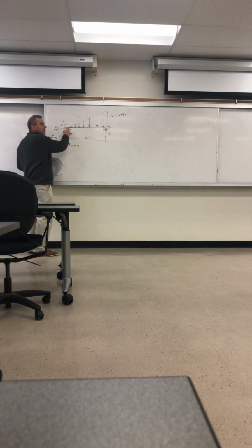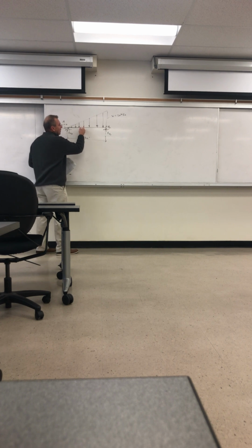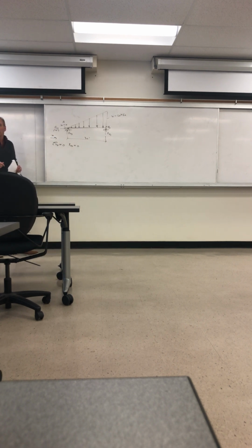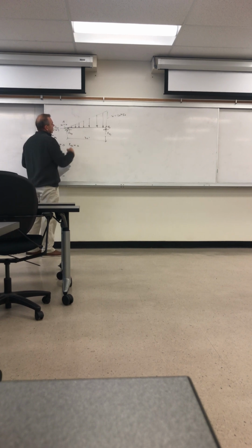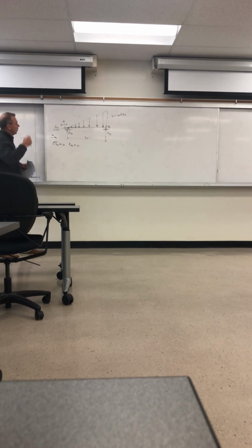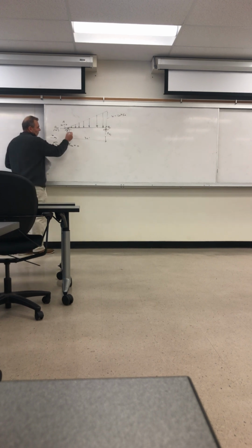So it's 0 here, no distributed load. At this point, the intensity of the distributed load is 10 kips per foot, and at the right it's 20 kips per foot, and it's increasing as we go. That's why we have to do something to recognize that distribution. In this case, it's a triangular distribution, and so we can solve for R sub Ay by saying the summation of moments about B is 0.